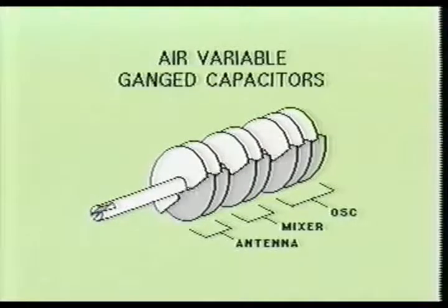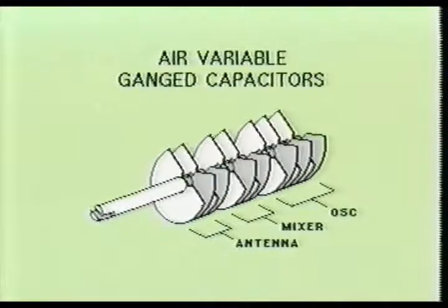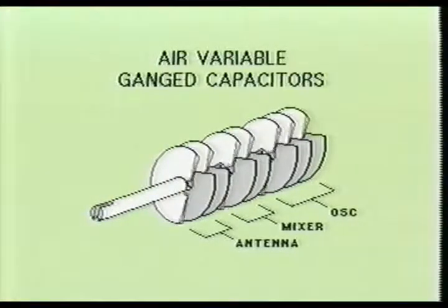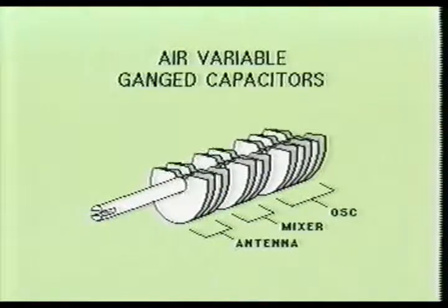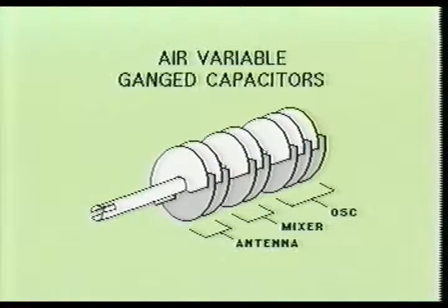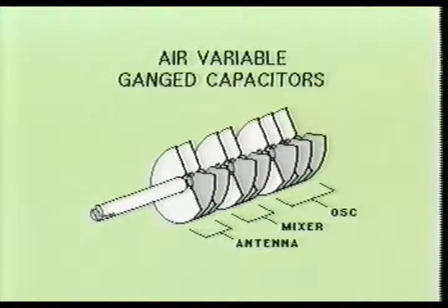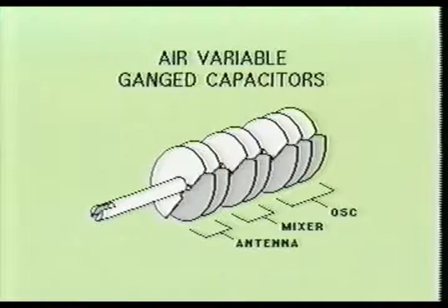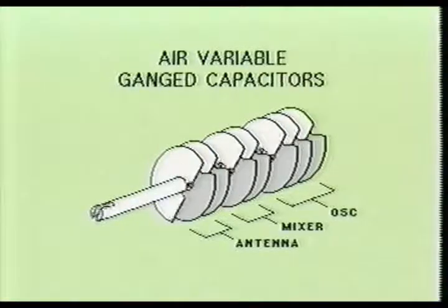As you can see, the UHF tuner would vary the capacitance of the tune stages instead of the inductance as was used in the VHF tuning devices. Also notice that the UHF tuner only controls 3 stages instead of the 4 stages controlled in the VHF device. The UHF tuner will vary the frequency of the antenna, mixer, and oscillator stages in the UHF tuning device.